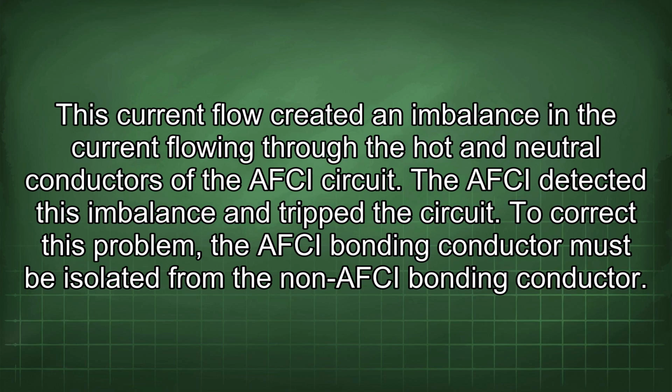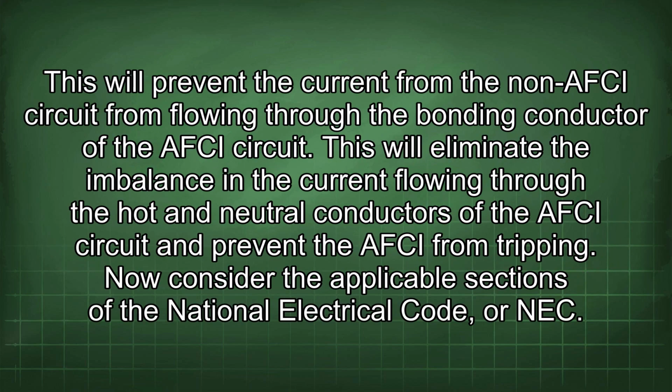To correct this problem, the AFCI bonding conductor must be isolated from the non-AFCI bonding conductor. This will prevent the current from the non-AFCI circuit from flowing through the bonding conductor of the AFCI circuit.